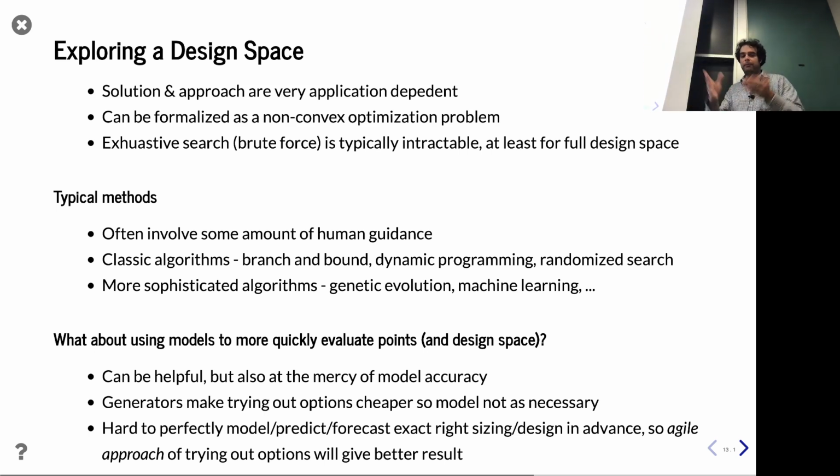And so, however you do this, at some point you're going to have a lot of parameters, a lot of design points you still want to evaluate. And the question is, how do you evaluate these? Well, with this class, we're pitching this philosophy of: make tools do the work, right? Set your Chisel parameters up, generate Verilog, pass it off to the tool chain, and let it run. If you want to do 100 designs, you do 100 designs, you put a cluster to work overnight, right? That's a lot of cycles.